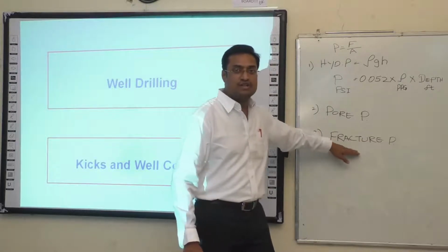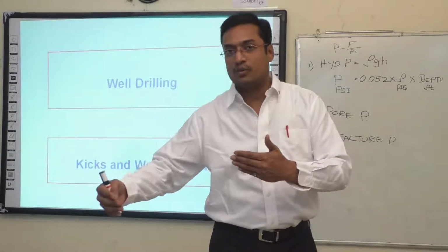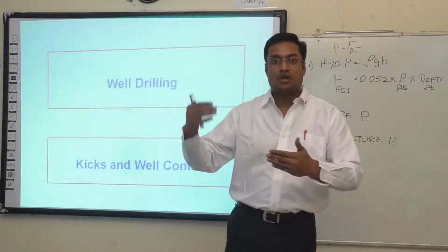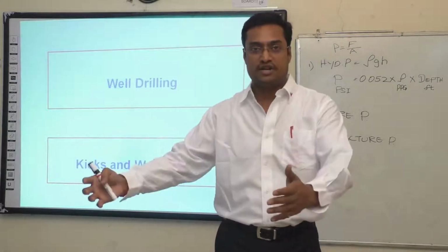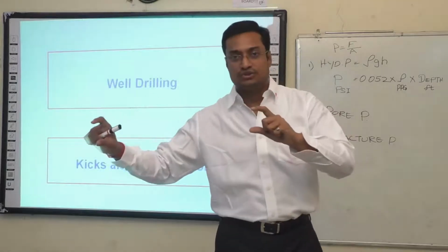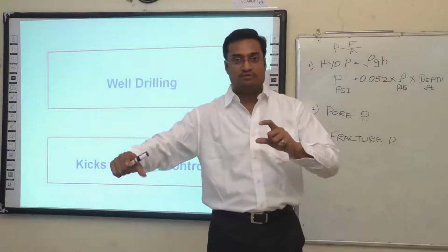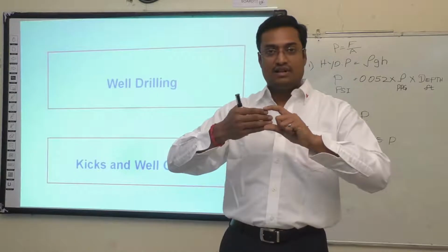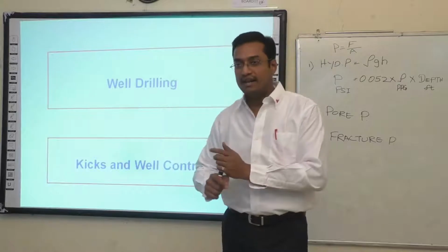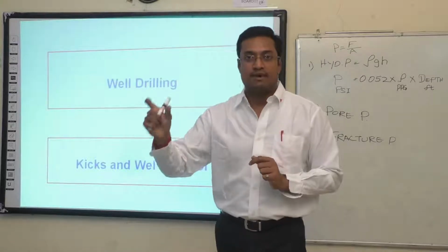If we fracture the formation, we cause more damage. If we cause more damage, we lose control over the well. It interrupts the drilling process. It creates more non-productive time. That means we try to do some operations to bring the well under our control, but these activities are of no use. We damage the formation, we create a problem, we solve the problem, bring the well back in control. Till we bring the well back in control, the time and money spent on the well is called non-productive time, which is basically waste of time and money.